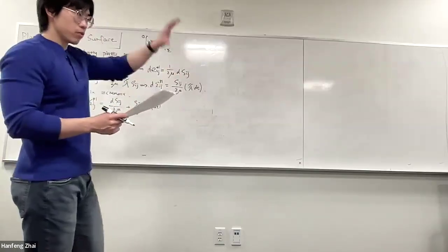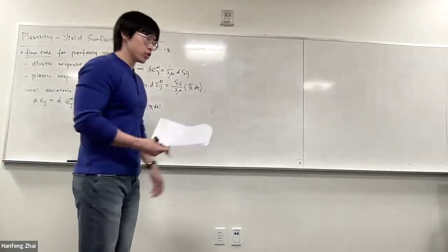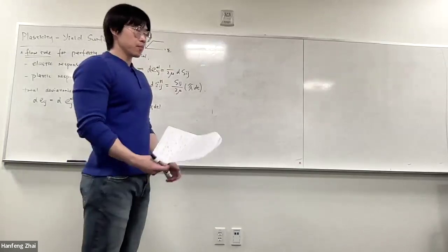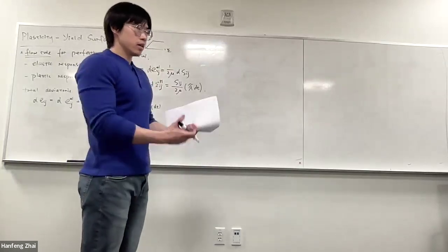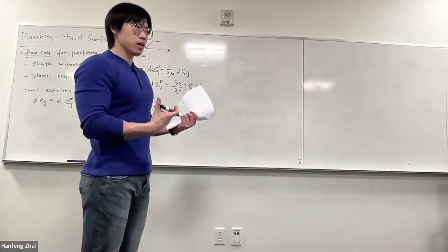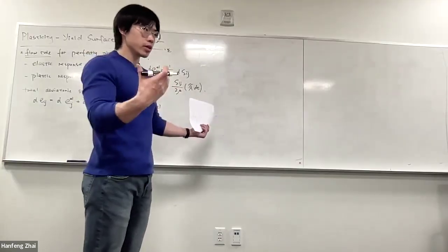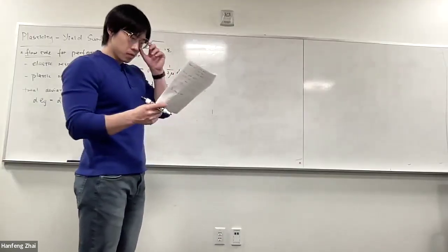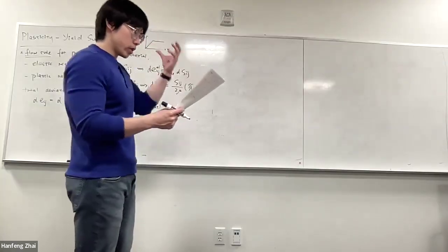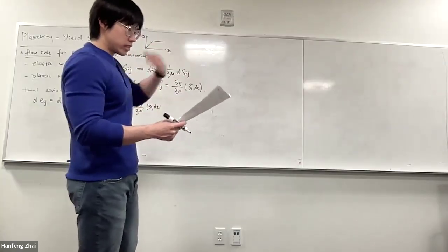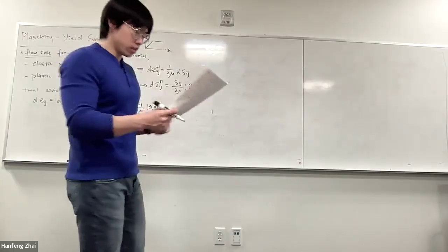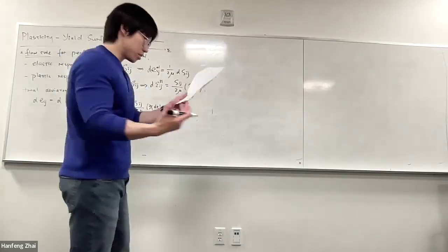Because for the first half of this video, we've been doing a lot of geometric interpretation under the principal stress axes or space. How do you interpret the Mises yield criteria and Tresca yield criteria? So how would you geometrically interpret the plastic deformation once you reach the yield point? I'll try my best to deliver this.